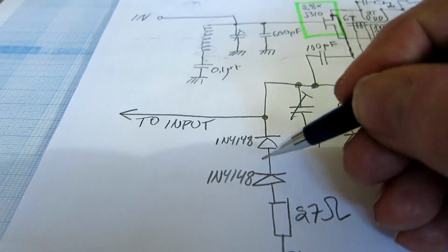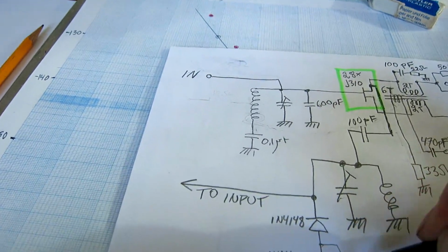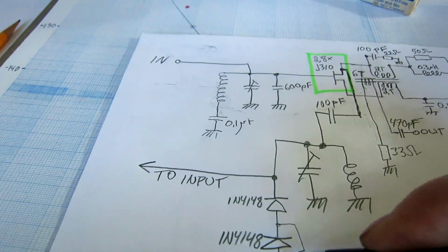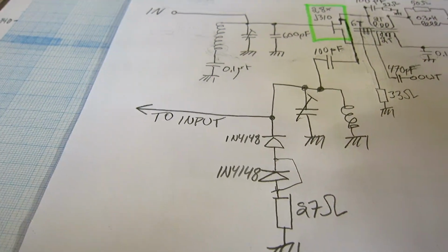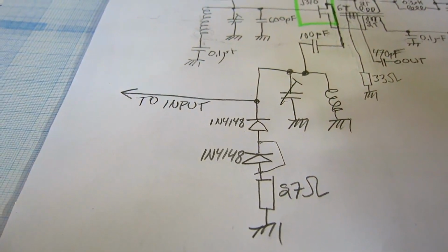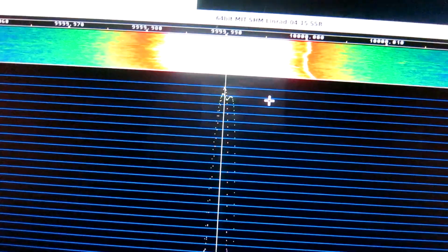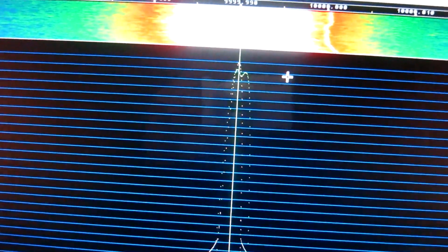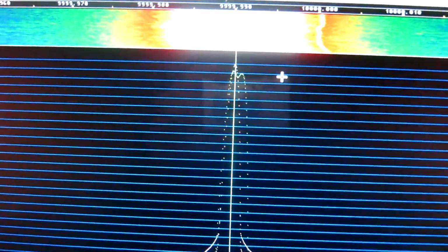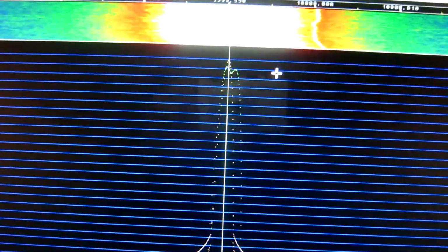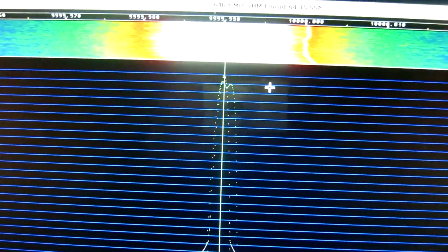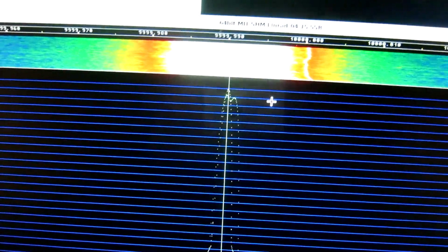I have shorted one of the diodes like this. That reduces the power by about 4 decibels, and that will perhaps affect the sideband noise somehow. The frequency has changed by about 1 Hertz. I have a feeling it is caused by something changing in the crystals. I wouldn't have seen it when using this unit as an amplifier. It would just be a small phase jump that would not affect the frequency.